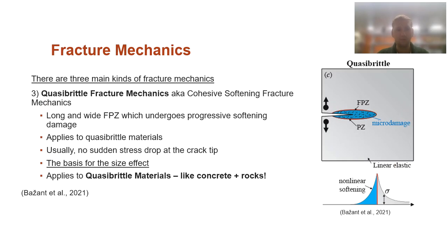But most importantly, we have quasi-brittle fracture mechanics. Kind of the lesser studied area here. We see a lot of stuff with LEFM, not much with quasi-brittle. In fact, we see so much with LEFM, we're about to talk about it next, because LEFM helps us define just about everything that's happening, and it's kind of easiest to put things in terms of LEFM. And we'll see that even Bazant adopts LEFM to create another version of the size effect down the road. But for our purposes in concrete and rocks, we can understand quasi-brittle fracture mechanics and quasi-brittle materials.